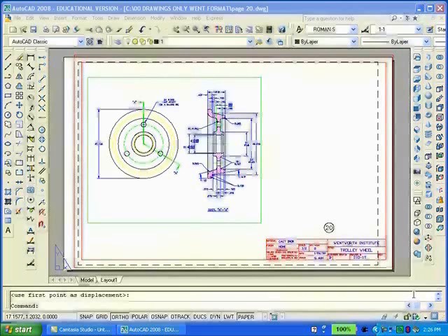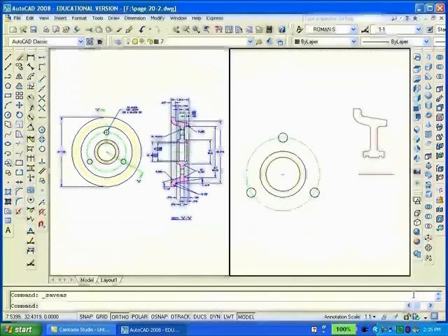This is tutorial 20 and we're going to make another solid model. This time the profile to be revolved will be at a distance from the axis. Also remember that I made one continuous polyline out of it using the polyline edit command. Of course I could have used the other method by just tracing over the profile with another polyline.